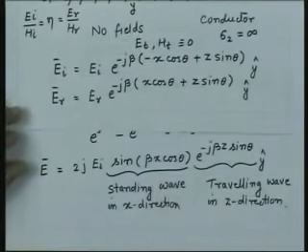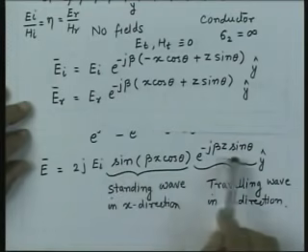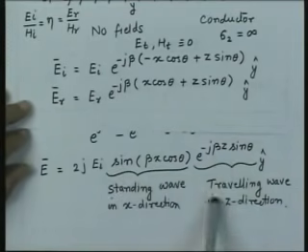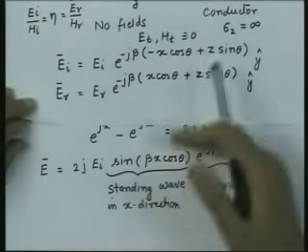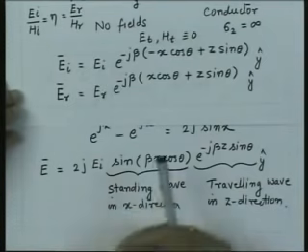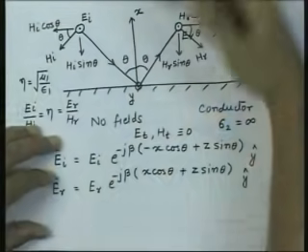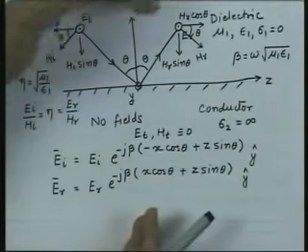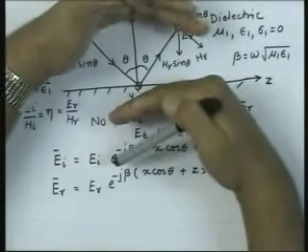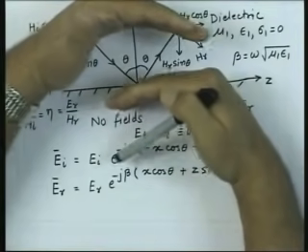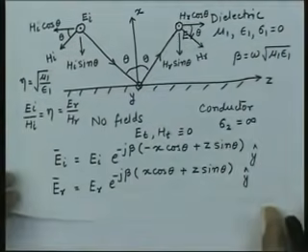So, this boundary, as this demonstrates, has a capability of guiding a wave along the z direction, because we are having a net travelling wave which is travelling along z direction. Precisely that is the phenomenon we are going to make use of to get a more guiding structure. That means I will trap the energy from both sides now. At the moment the energy is not trapped, energy is travelling into this semi infinite media. We will try to trap the energy even from this side, so that energy propagates in the two planes, something like this, which we call the parallel plane waveguide.